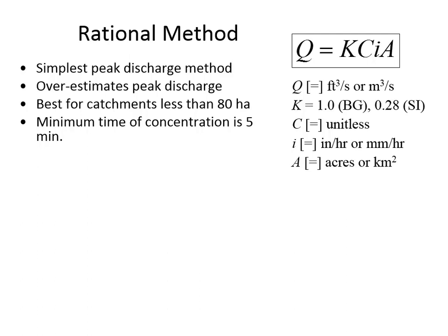Well, to estimate time of concentration, you have to think about where is the point furthest away from that drain in terms of flow time. Maybe the flow is going to go all the way from here across the surface before it finally gets to the drain. And you have to know what the travel time is from the hydraulically furthest point in order to select the rainfall intensity that you use as the I.